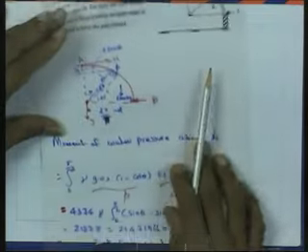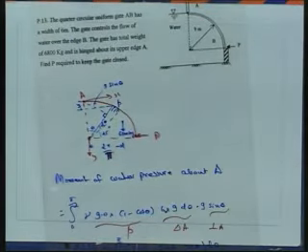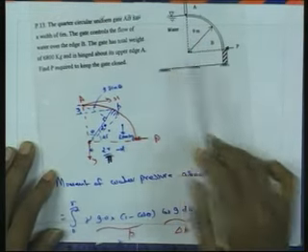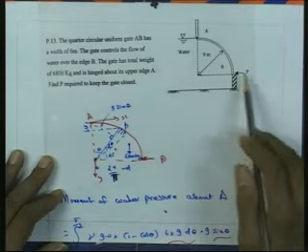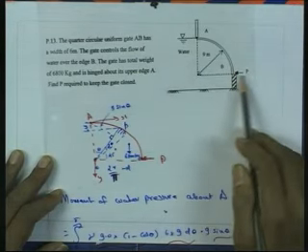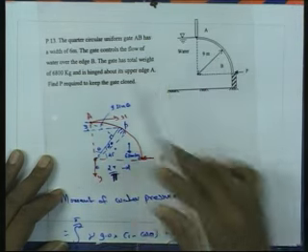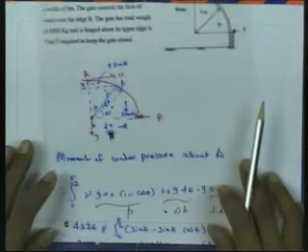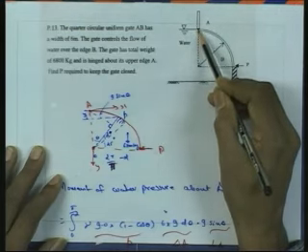If you want to find the pressure P, now we will be considering all the forces as far as this gate is concerned. The forces here are the water pressure acting from this side, and the force which we want to keep it closed, this P, and then the weight of the gate, 6,800 kilogram. If we want to find P required to keep the gate closed, finally we will be taking a moment of all the forces about this location, this point A.